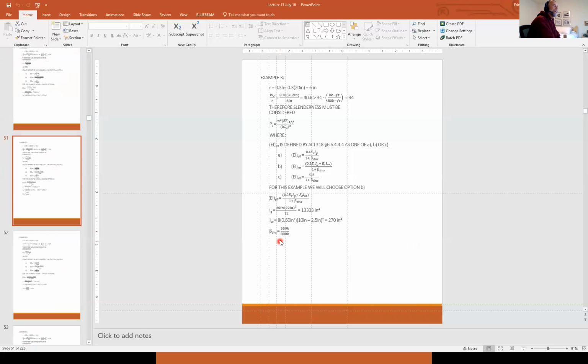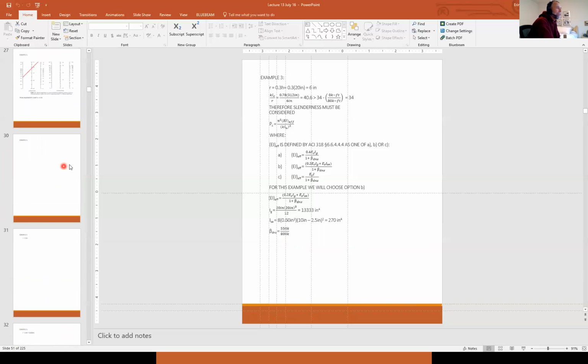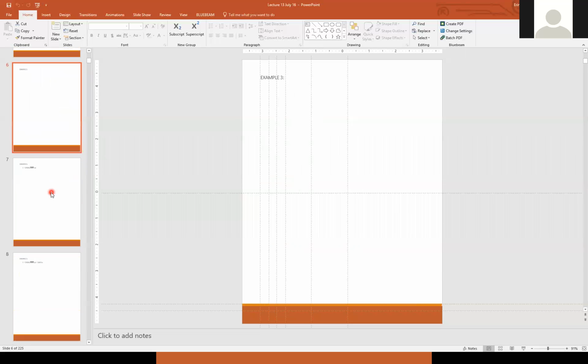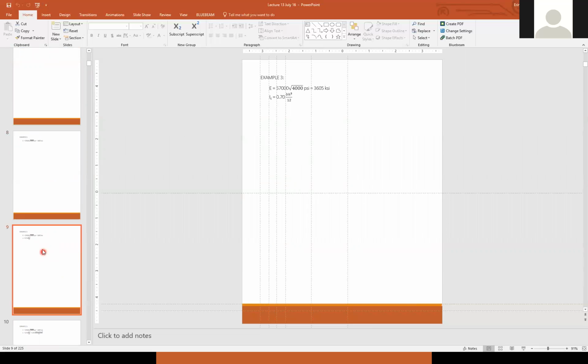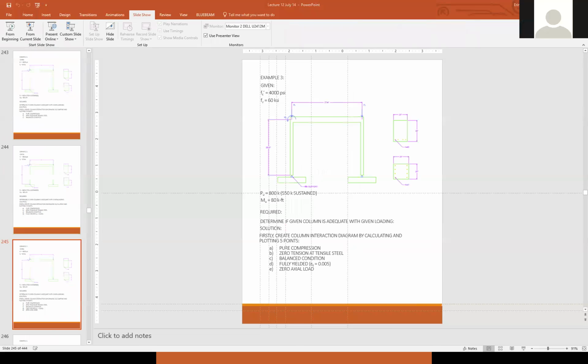Okay, so beta DNS, you're right. I didn't put the variables here, but this is the axial load sustained over the total axial load. And where that comes from... was that the last? No. I believe that was from the last lecture. Oh, yeah, you're right. That PU equals 800K. And there it is, right there. So PU is 800K and 550 of it is sustained.